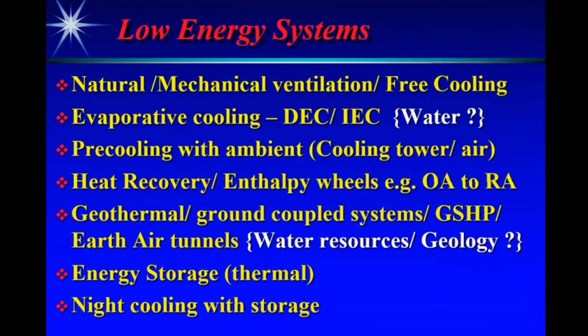The second aspect from the sustainable perspective is to have systems which are based on low energy and not very highly energy intensive using electrical energy. So the first thing which we should look for whenever we think of low energy systems is to provide natural cooling. If the ambient is moderate, if the outside temperatures are suitable, humidity is suitable, then we can just bring in outside air into the space for catering to our cooling requirements. So ventilation air is used in such cases. So this is called a free cooling option because we are not investing much in this. Although there may be a small blower, etc., required to bring in free air if there is no wind outside in the environment.